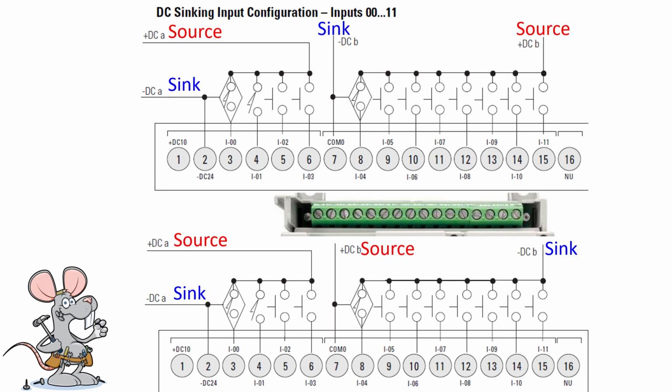Where it will come into play is if you build a learning station and you use some of the practices that I do where I provide extra terminals for outputs or inputs that aren't connected to the simulators. In other words, they just go to a terminal block and then you can hook up your own sensors and output field devices for your own edification and learning experience. Then it matters because you have to know what you can do as far as sinking and sourcing goes.